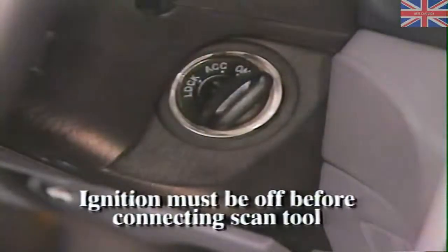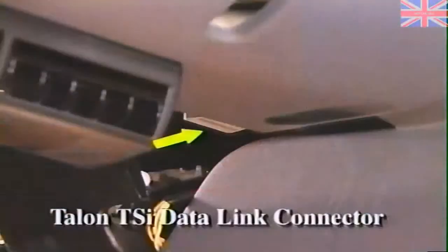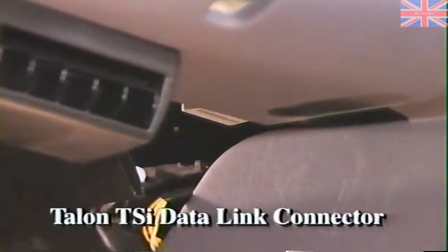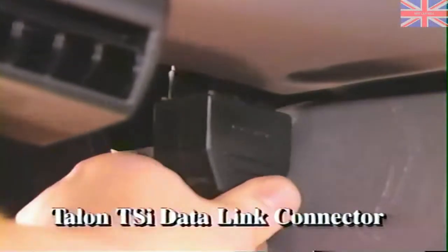The next step is to check for diagnostic trouble codes with the scan tool. Always make sure the ignition is off before connecting the scan tool, as recommended by the service manual. There may be 1 or 2 data link connectors, depending on the vehicle. Data link connectors for 1994 and 1995 vehicles with airbags are located below the instrument panel above the accelerator pedal.